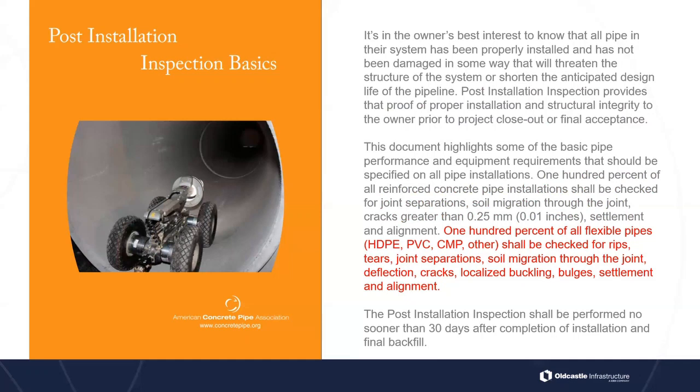So it is highly recommended that you video concrete pipe and flexible pipe, whether it's plastic or metal, and do the mandrel test for flexible pipe. No mandrel test necessary for concrete pipe because it doesn't deflect.